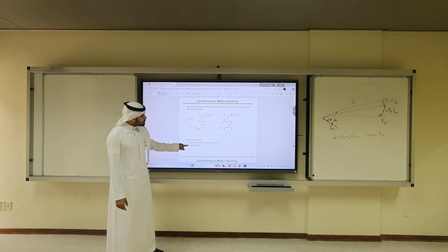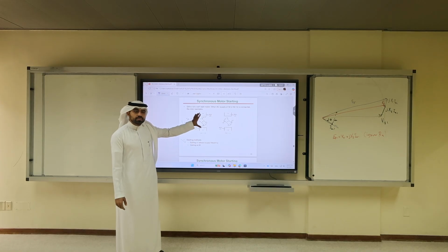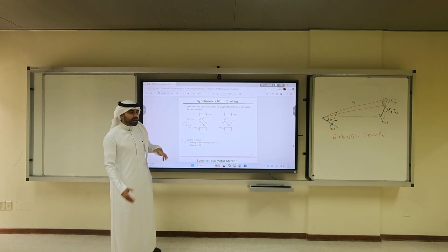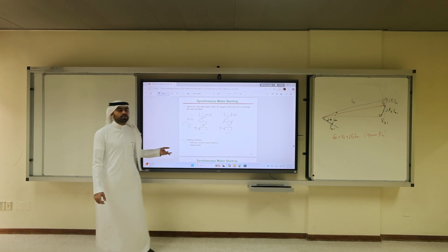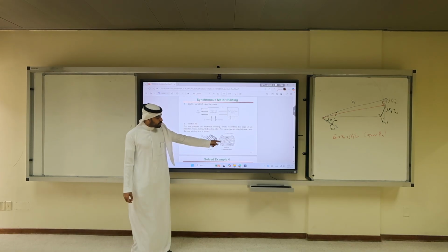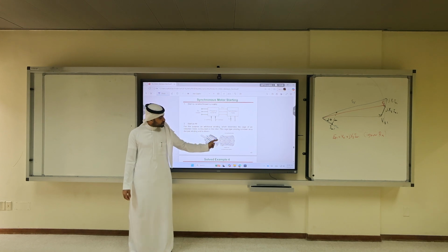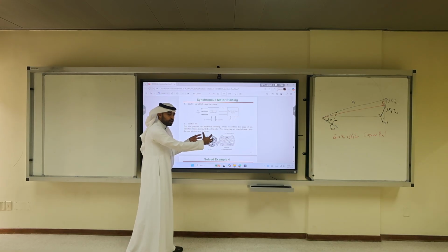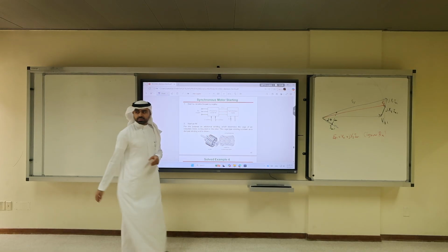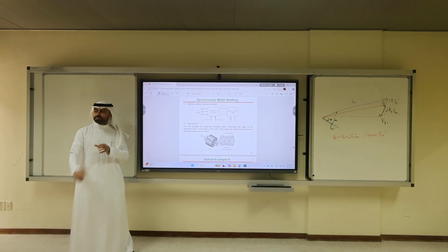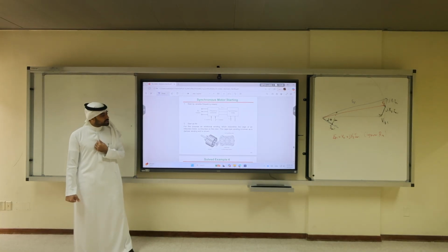The other method is starting the synchronous machine as an induction machine. This is achieved by some sort of supplemental mechanical components. You remember the squirrel cage, which is bars made of aluminum with end rings that are short-circuited. You put the excited rotor of a synchronous machine in a cage.